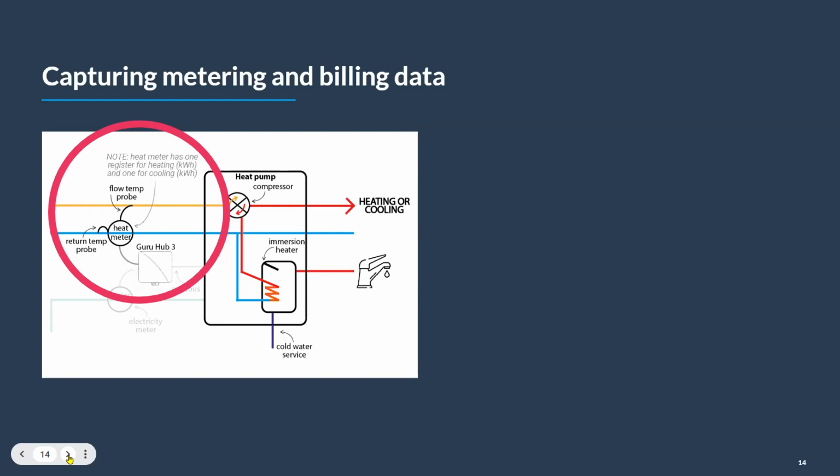You need to make sure that meter has 2 registers that will automatically switch over. Not all dwellings will have heating and cooling in them, but we're seeing more and more that do. So make sure the meter can capture both, because quite traditional thermal energy meters have a single register just for heat, so any cooling will be missed. On top of that, make sure the meter reader can also read the 2 registers inside that meter.